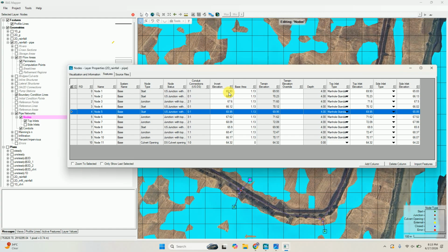You want to create a manhole type structure where water will go in the barrel, and it will go through the pipe and dump somewhere. So you have to dig the trench for a particular depth, and you have to place your pipes in the trench. So for that you have to dig till this much elevation. So this is the invert elevation of each node.